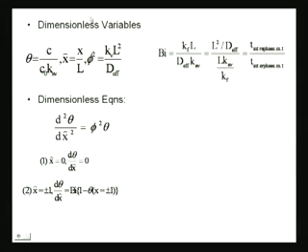So, when I write in terms of these two dimensionless variables and these two dimensionless numbers, my equation comes out the same: del 2 theta del x hat square equals phi square times theta. The boundary condition is x hat equals 0, del theta del x hat equals 0, and at x hat equals plus minus 1, del theta del x hat equals Biot number times 1 minus theta. Okay. Krishna Pratap, you will tell me, that is the second boundary condition, completely correct?